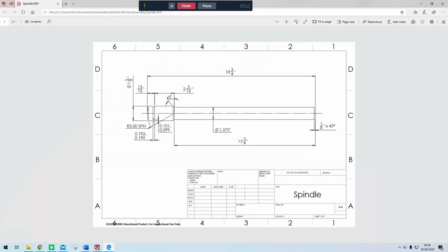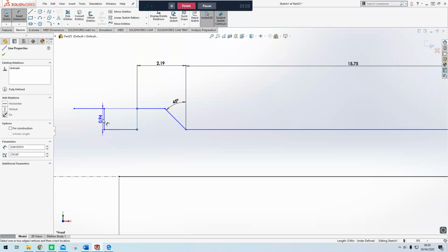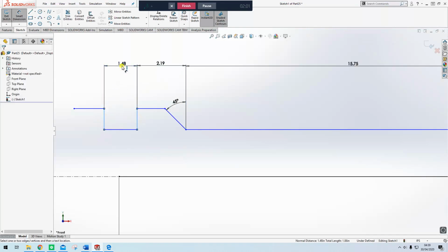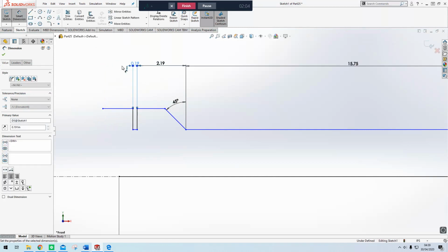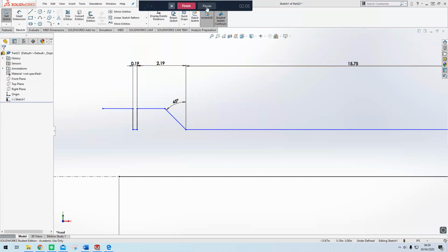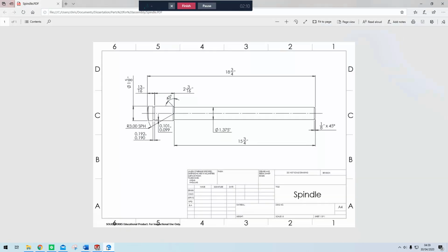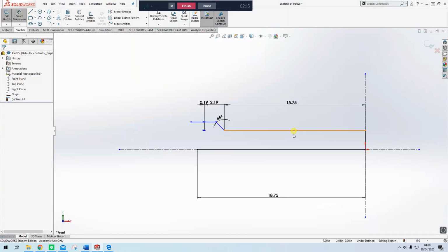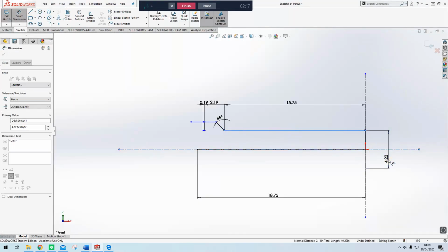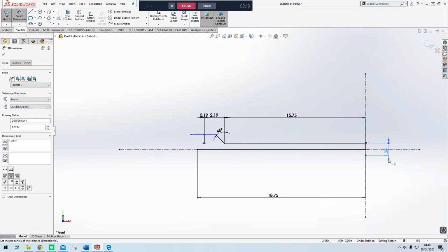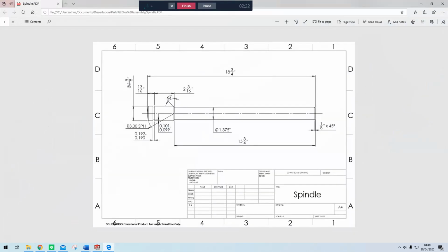Now we have the width here, and it's a tolerance, so we're going to need to use the figure in between, and that's 0.191. Now next we can look to dimensioning the diameters. So we have 1.375 here. And we have 1.58 for these two lines here.